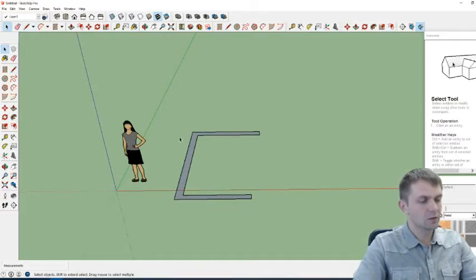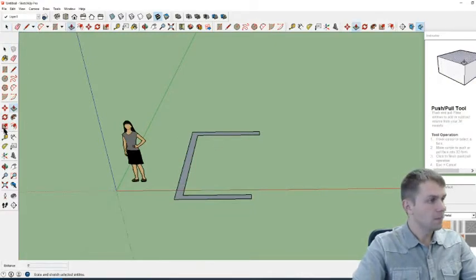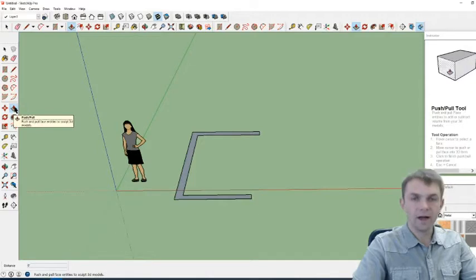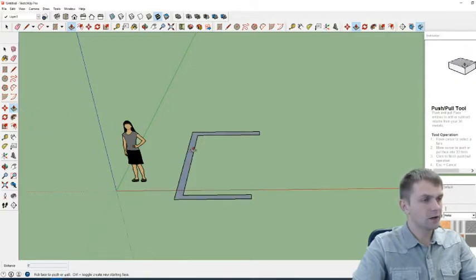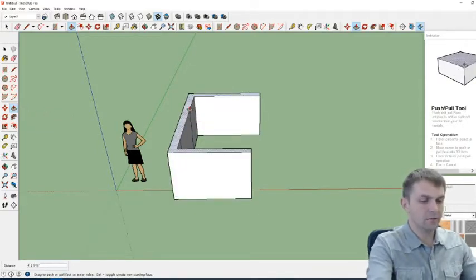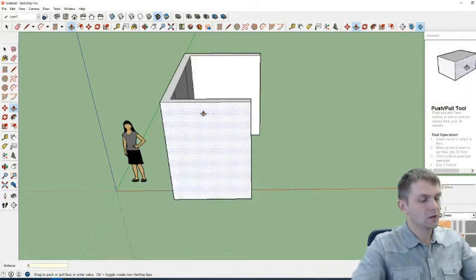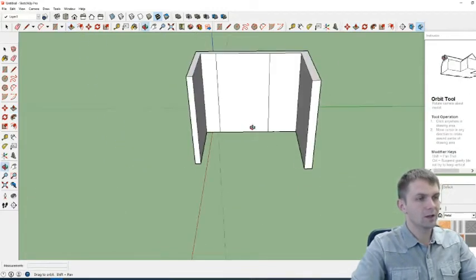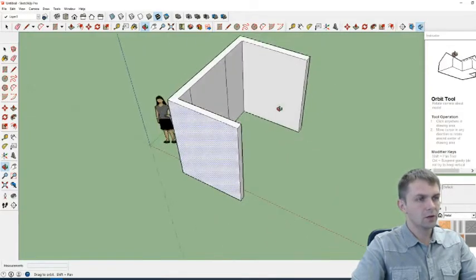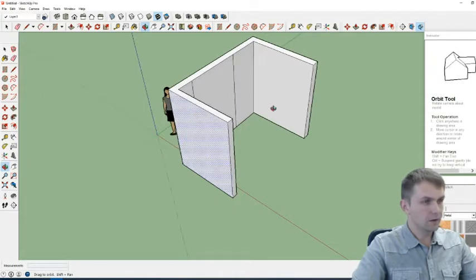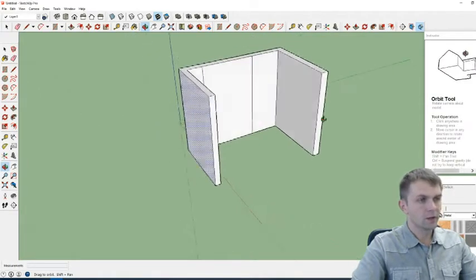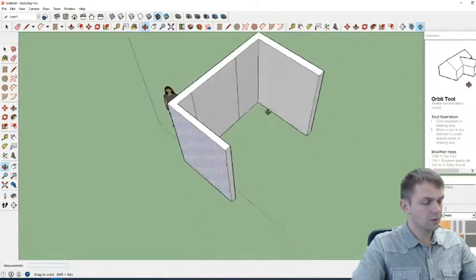It's cool. So we press P for pull, and this is basically this icon right here. The height I have, my total height is 96, so I got that. As you see, where we did the lines, the door is already preset for us, so it's easier to play with that. And yeah, we continue to work on this floor plan.